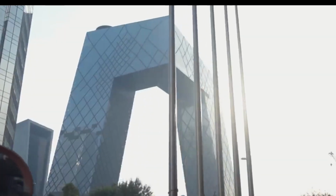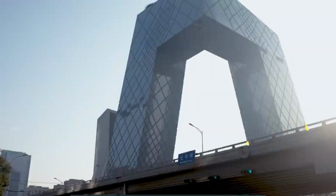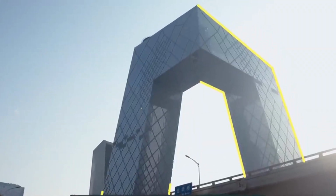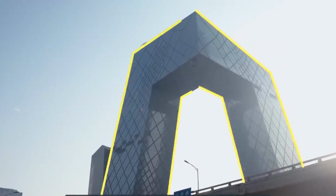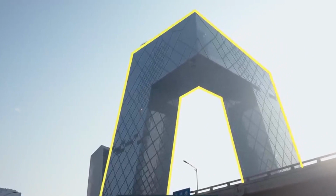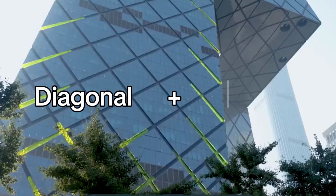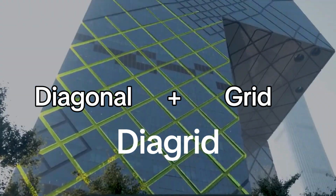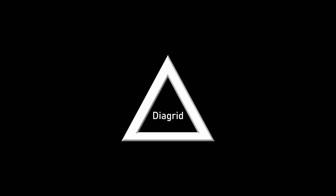CCTV headquarters applied the diamond grid structure to overcome the disadvantages resulting from unusual shapes and loads. The diamond grid structure system is a combination of diagonal and grid, also called an ultra-large diagonal structural system. A diamond grid is a triangular module that uses beams and bracing members instead of a vertical column and is a structural system that resists vertical and horizontal loads.